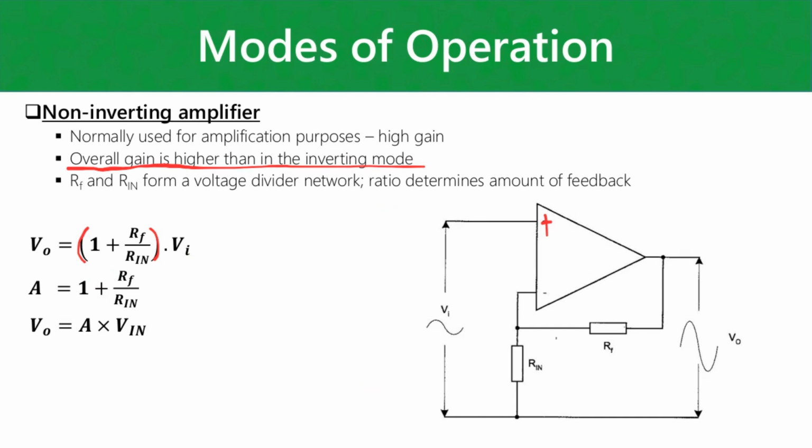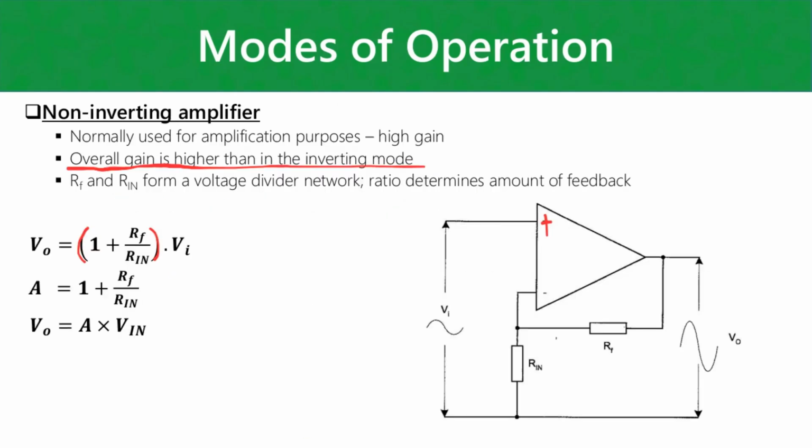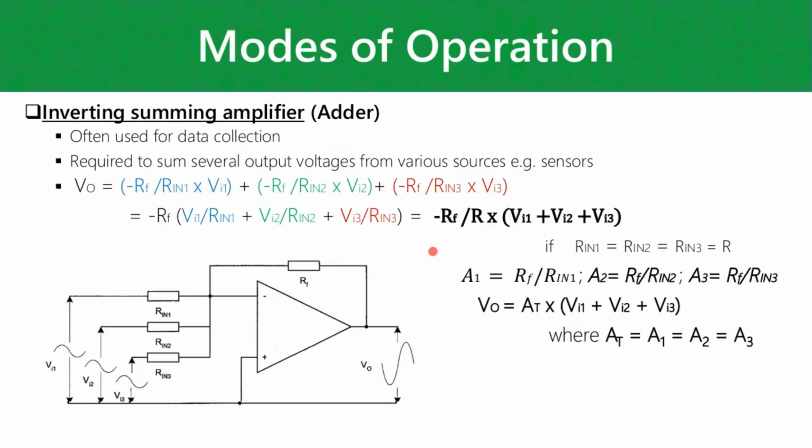But anyways, I think let's maybe take a look at a quick example as well. But I think let's maybe do the summing amplifier first, because the summing amplifier is essentially an inverting amplifier with multiple inputs, right? So you can use superposition in this situation to basically calculate what your output voltage is. So you can go and calculate the contribution of each input voltage in what output voltage it would result in, and then just add everything together. All right, so that's essentially what's done here.